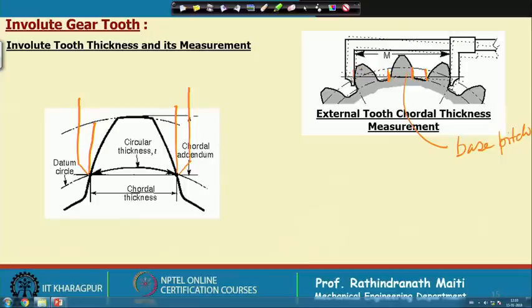So, this means that if we consider 2 base pitch minus the thickness of the tooth at base, or one thickness at the base, that will be the total measuring length. So, depending on teeth, and if we know the base pitch, this dimension should be known, because this surface is touching this involute profile here. Okay. So, this will not have the error like measuring at a depth.